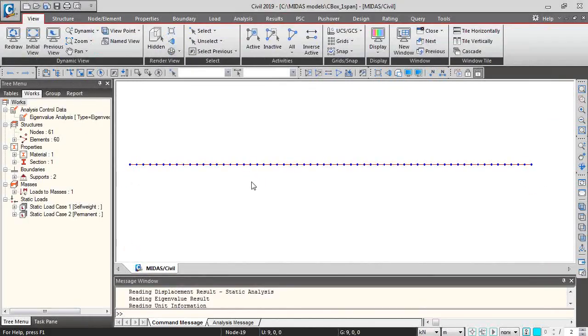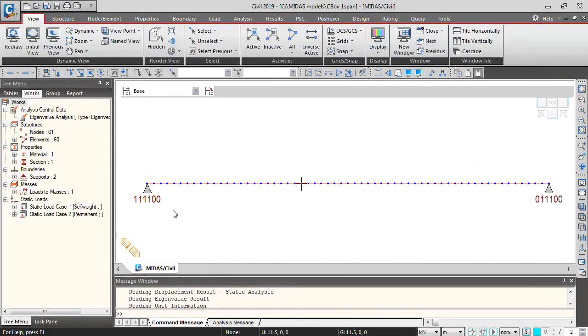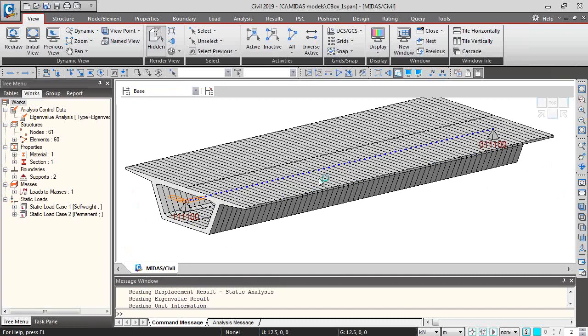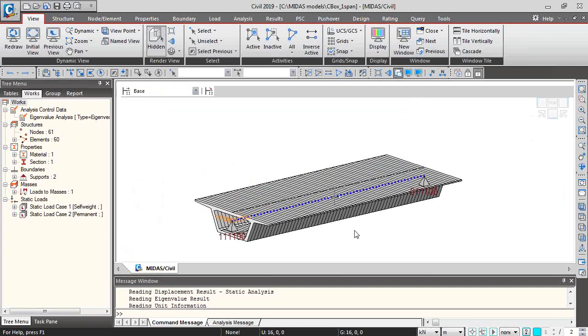I've prepared a very simple model like this one. It's basically a beam element representing this concrete box, 30-meter span, and I've subdivided the beam element with nodes every half a meter. My boundary conditions are simple supports on both sides. It's rotationally free because I'm assuming we have a couple of bearings at each support, and the axial load is fixed on one of the ends. Just to show more or less how that looks, that's this section, and that's a 30-meter single supported span.